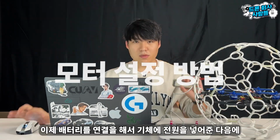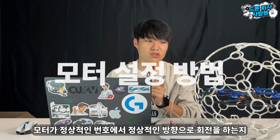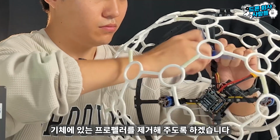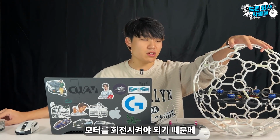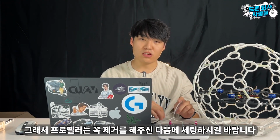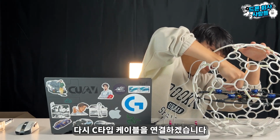Now, connect the battery to power the aircraft and check if the motors are rotating in the correct direction with the correct numbering. Let's remove the propellers from this aircraft. The reason for removing the propellers is to prevent any accidents since the motors need to be rotated. So please make sure to remove the propellers before setting it up. I will reconnect the C-type cable.